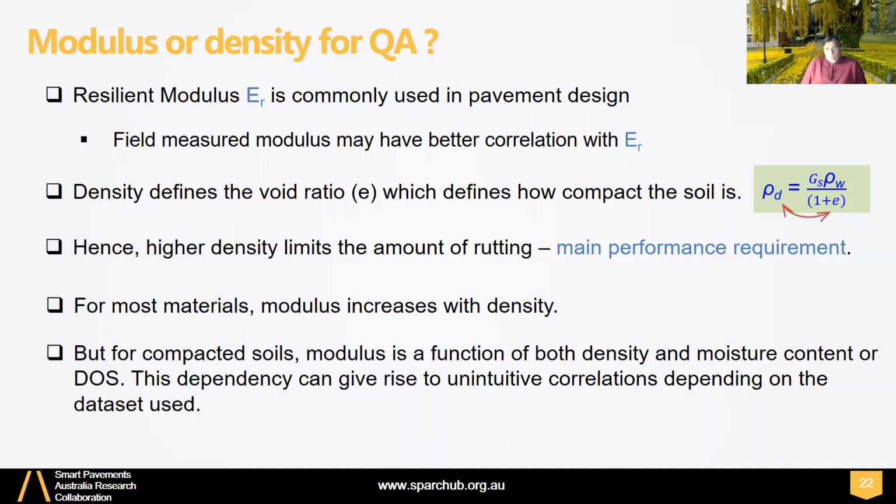However, if you go to asphalt, the situation reverses altogether. You will have asphalt dependent primarily on temperature, and moisture has less effect. So if you want to simplify and capture essential physics rather than complicating your equations and making life unnecessarily difficult, we can probably use moisture for UGMs and subgrade, and temperature for asphalt. However, more research is underway on this topic. Then we have another question.